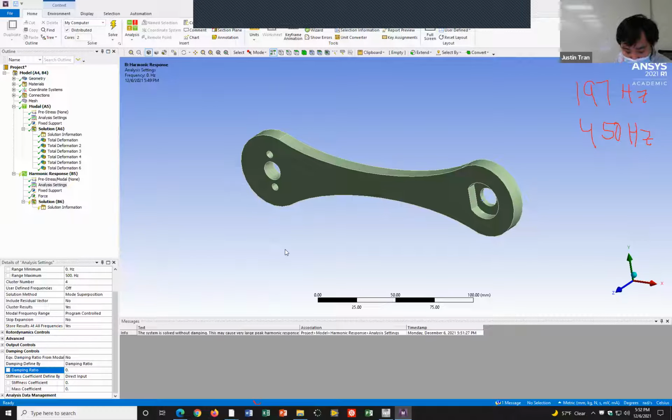Okay, so what that is basically saying is that without any damping in the system, and damping represents things like friction and internal imperfections in the solid, what happens when you reach resonance is that the deformations go off to infinity. There's really nothing that's inhibiting the deformations anymore. Sometimes you might want that, but a lot of times you actually want to keep the deformations bounded.